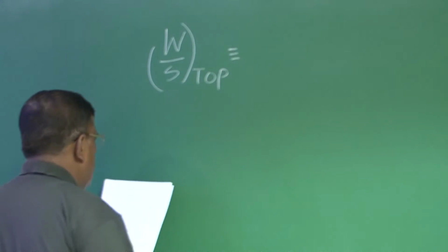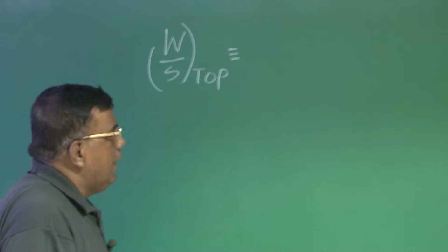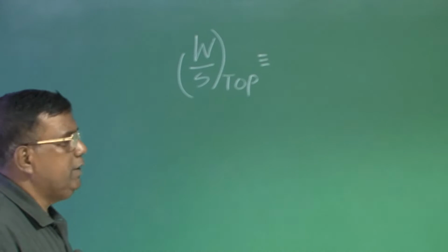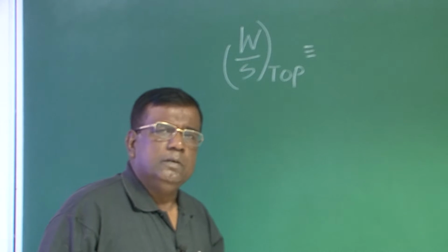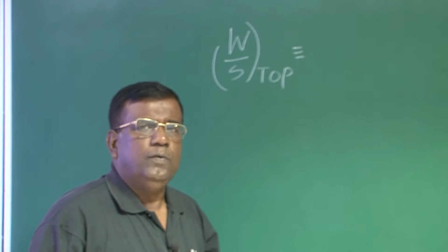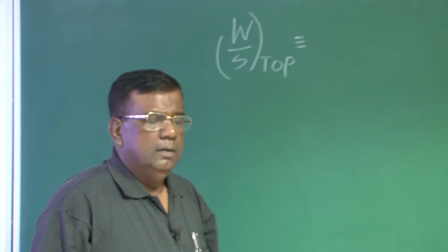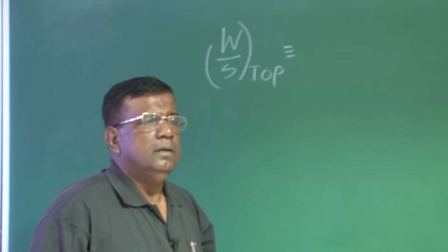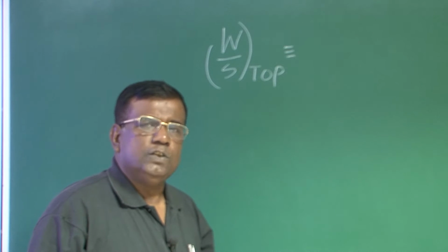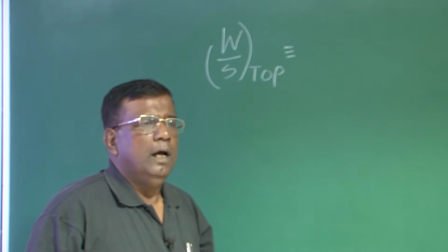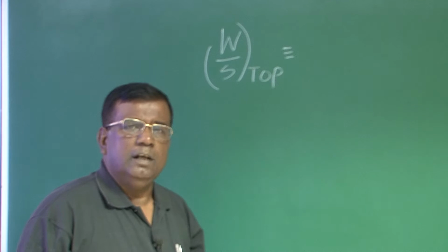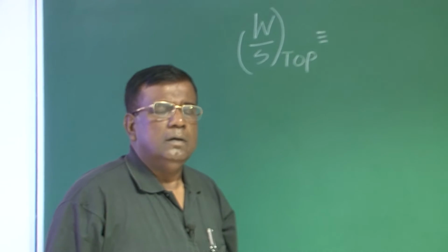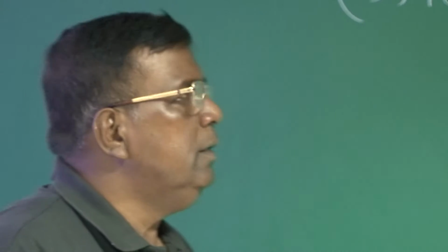After having the understanding that when I am talking about wing loading, takeoff, in takeoff the most important thing is how fast I achieve the V liftoff or takeoff speed. That gets connected to V stall, and when I say how fast, it means acceleration. That again connects this to T by W. All these things we have seen.